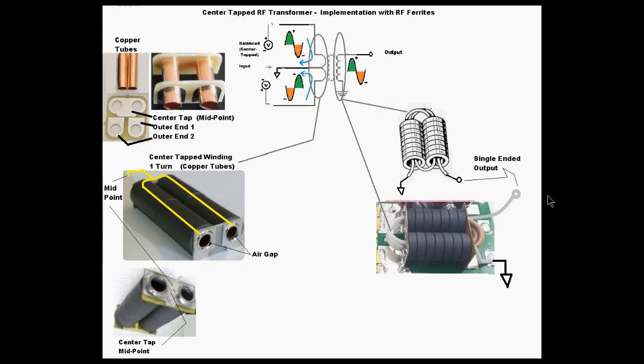I just want to mention that some of the good old boys still refer to this style of transformers as stack-pole transformers. That name comes from the vendor, Stackpole, that made the ferrite beads for these. But we're going to use a more meaningful name. We're going to call them ferrite RF center tapped transformers.